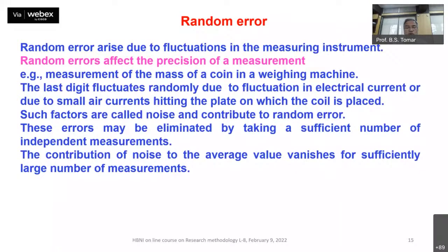Okay. So when you have the measurements, the measurement may introduce different types of errors. And so you should know how to correct them. So the errors could be random. Random errors arise due to fluctuations in the measuring instrument, or your personal errors also come in. Different operators will have their own different ways of handling the equipment, so you introduce errors in that.